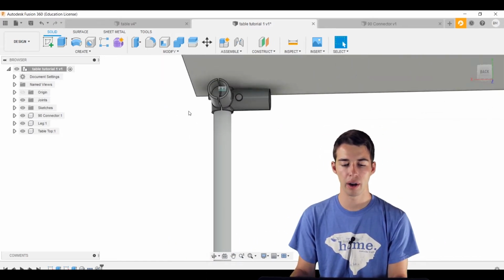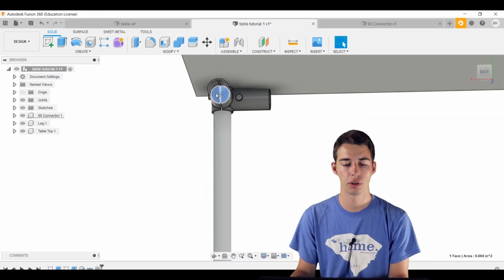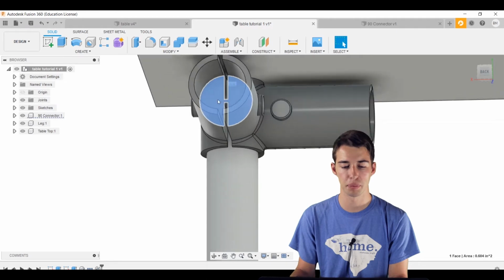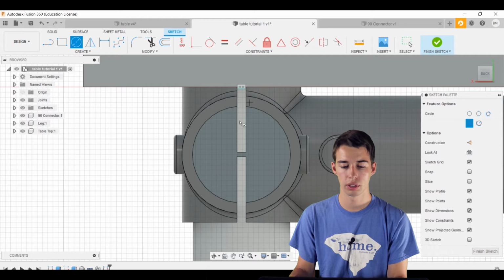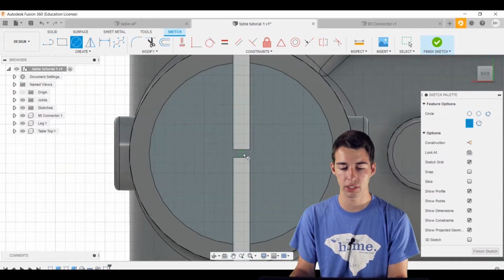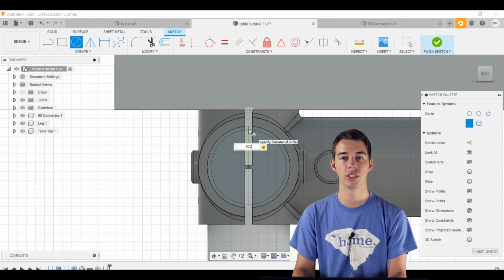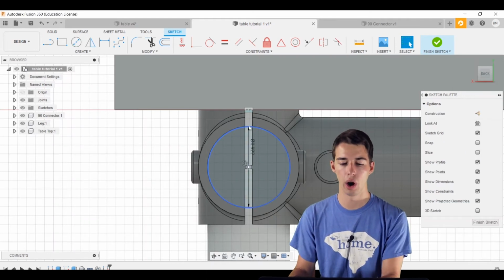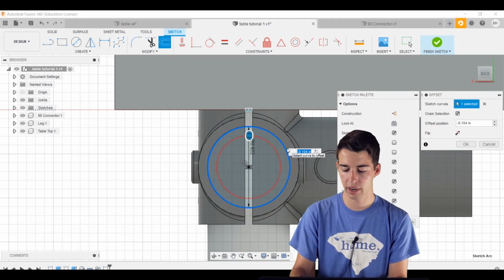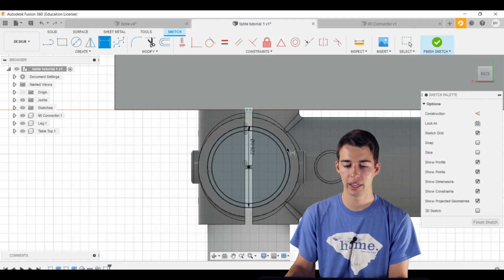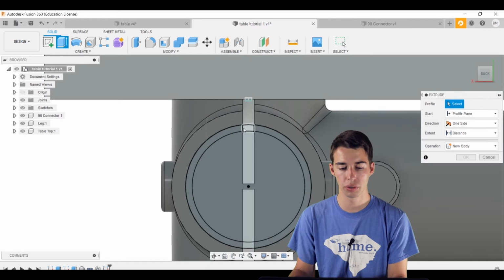So then from here, I'm gonna create the crosses that come off of that. This is similar to the last video. I'm gonna select this inner plane of our connector, create a sketch, and then click C to create a circle on this, and make sure that snaps to the center point. Pull that out, 0.922 inches for the outside diameter, and then O to offset. Click on that outside diameter and then pull it on the inside, -0.047, enter. And then we're gonna finish that sketch and then click E to extrude that.